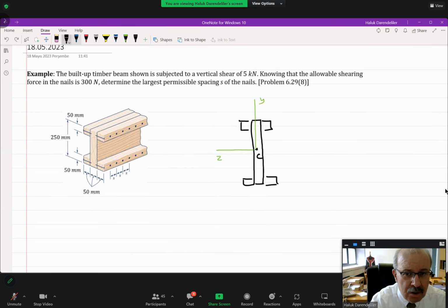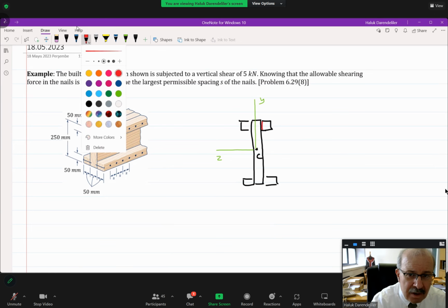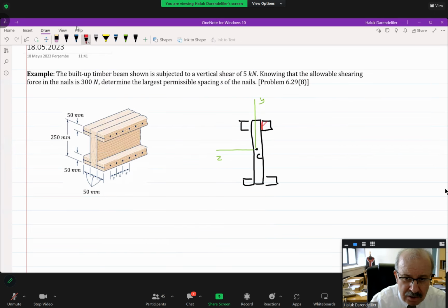You remember we talked about this last week. Let me select the region which divides the body into 2. This red line divides the body into 2 and leaves this separate from that. So now we are separating this cross-sectional area from the remaining. This cross-sectional area's centroid is somewhere here, and its distance from the neutral axis is y bar, equal to 100 millimeters as clear from the figure. And this is also the neutral axis here.